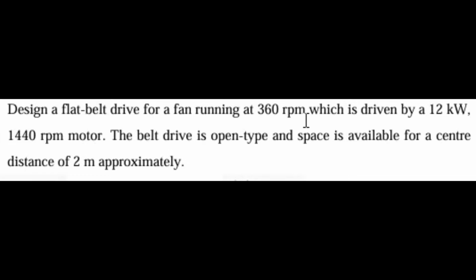So you have to design a flat belt drive for a fan which is running at 360 rpm, which is driven by a 12 kilowatt 1440 rpm motor. The belt drive is open type and the center distance is 2 meters. So we have to design a flat belt drive. That means we have to find all the parameters. Now let's look at the solution part.